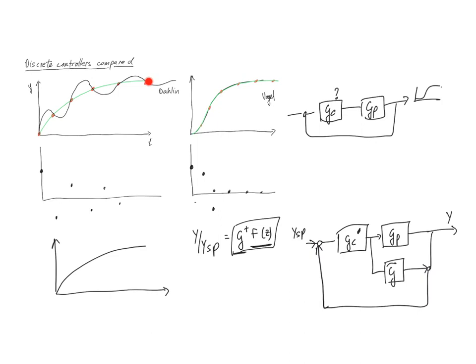We guess a prototype, design a controller, see whether that controller led to ringing, and then we had to maybe stick a plaster on it by neglecting the ringing poles in the case of the Dahlin. In the case of Vogel, we know that for a wide variety of parameter values, we end up with a relatively reasonable controller. However, the downside of the Vogel controller is obviously that we have a slightly more complicated prototype. In the case of IMC, we will be designing GC star, and we will be simulating G tilde.